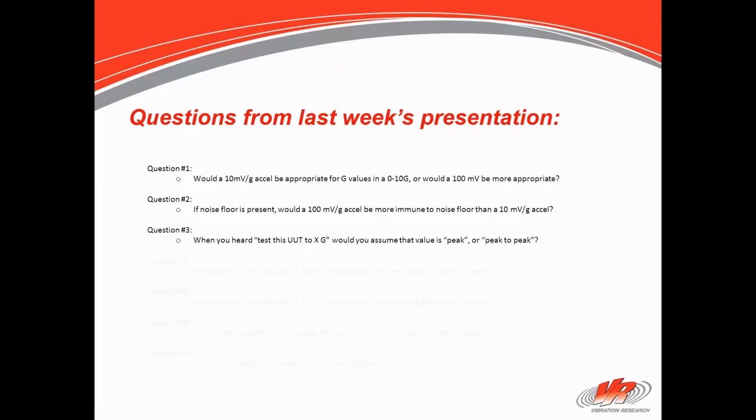A whole seminar could also be given on sigma clipping. My platform is you should never sigma clip. It's said that you need to sigma clip to protect the amplifier. While there may be some truth to that, really, you should look at it from the point of view of: I want to test my product, I should have true random going out there. And true random is going to produce 4 sigma, 5 sigma peaks.